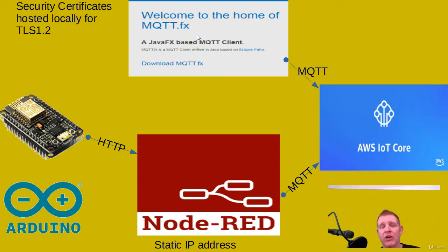Now, after that, we're going to go through a full demonstration using our ESP8266 or ESP32. Both will work with Node-RED. Node-RED is also free software by IBM. There's two versions of Node-RED. There's a cloud-based static IP version and a locally based dynamic IP version. I'm recommending you use the cloud-based static IP because it's much easier to deal with because you don't have to constantly redirect your device via HTTP to a new address once it gets dynamically allocated by whoever you're paying for your ISP host.